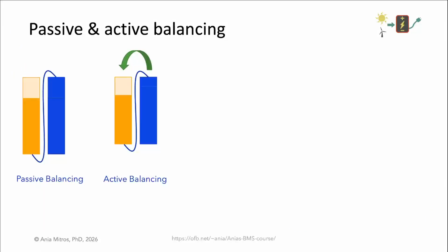Passive balancing is the most common approach to balancing, drawing energy from the highest cells through a passive element, namely a resistor. The energy difference is dissipated as heat. This is a lossy method. It's also the industry standard approach.